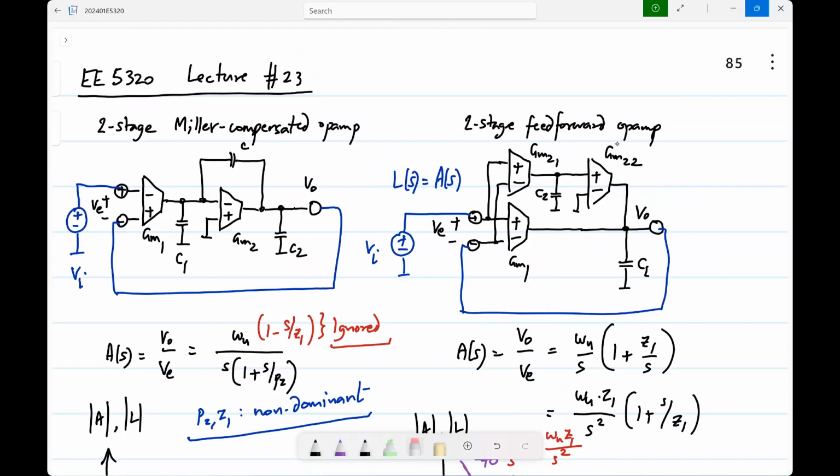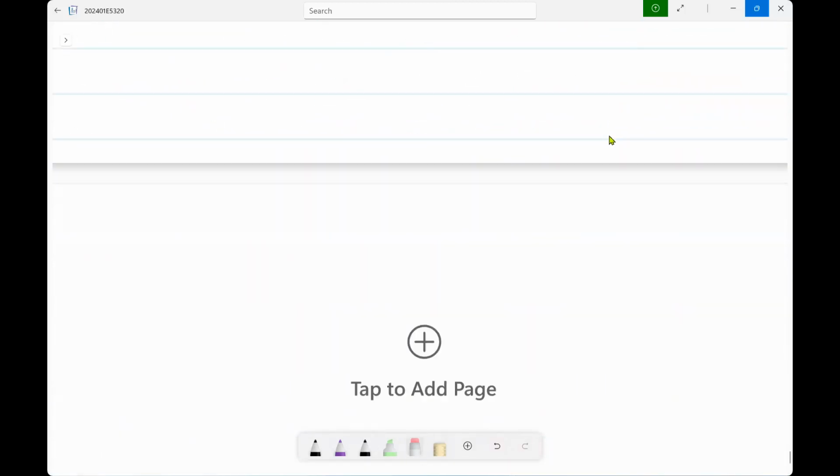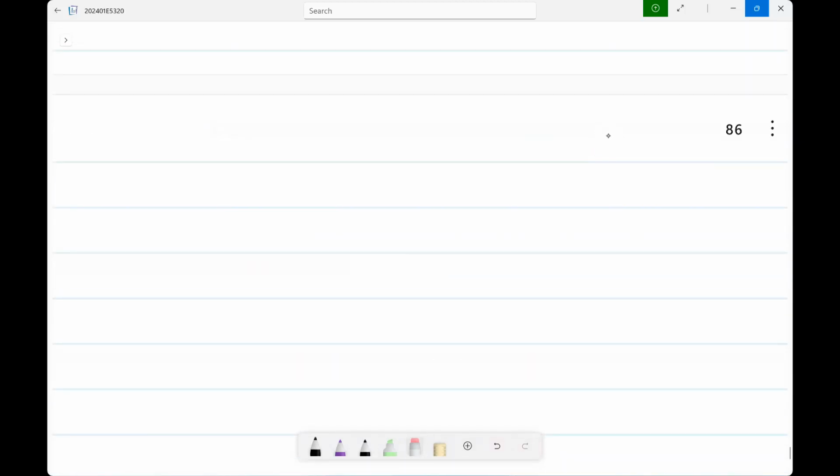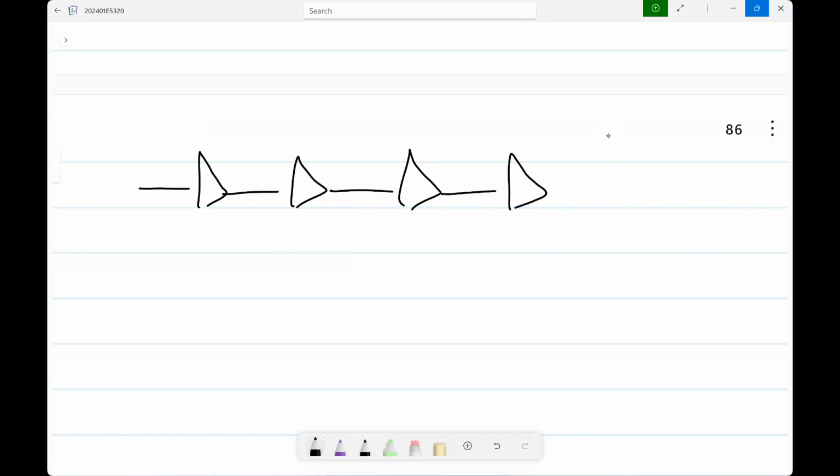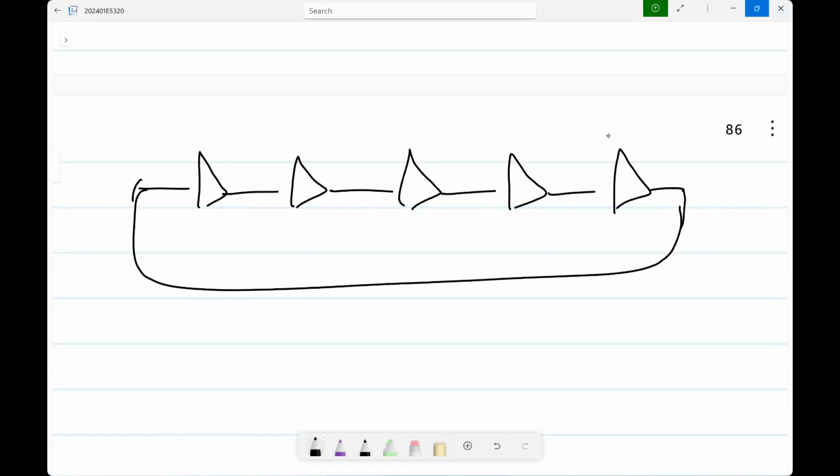Very high loop gain is essential to reduce the error. Error meaning the virtual short voltage, right? But to stabilize it, you need to have multiple local feedbacks. In general, the scheme may look like this. I'll just show this schematically. This is not very important here. You have some feedback loop like this with many stages, but this will be terrible for stability.